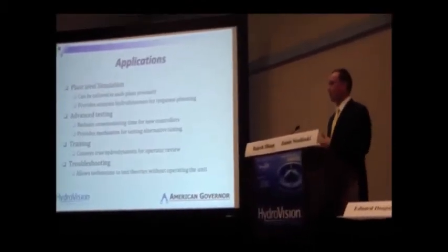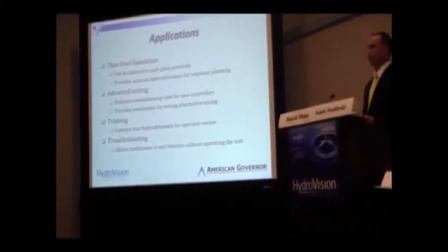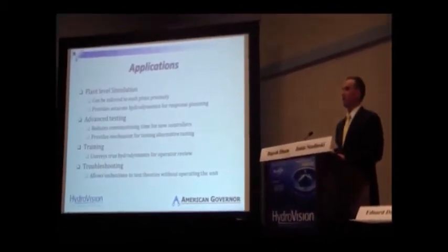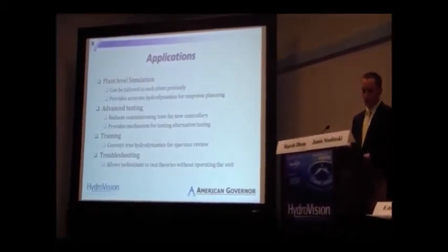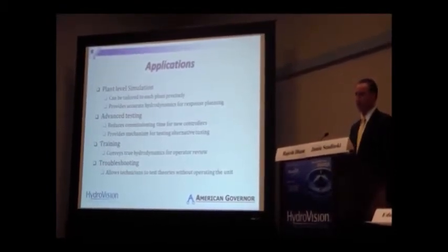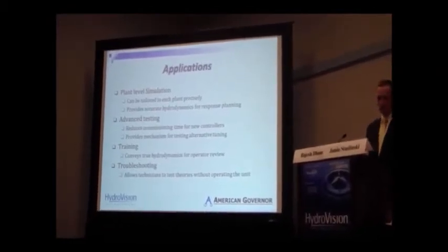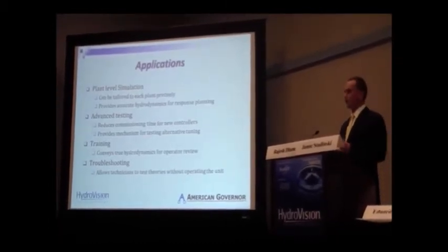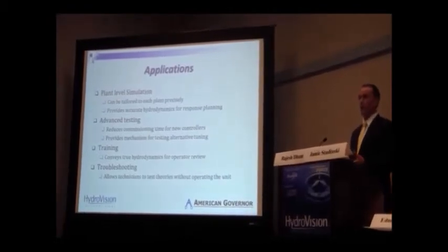So really, the cool thing about this whole process is that it's repeatable, and it can be really tailored to any particular power plant, especially pump storage facilities or other standard generating facilities that would incorporate some interesting hydrological components. We can take this methodology and apply it to any number of plants and provide any end user essentially the virtual version of their plant. This can be utilized, as we've done in this case, for hydrodynamic response planning. We can see what we need to do as far as PID gains, as far as our megawatt feed forward